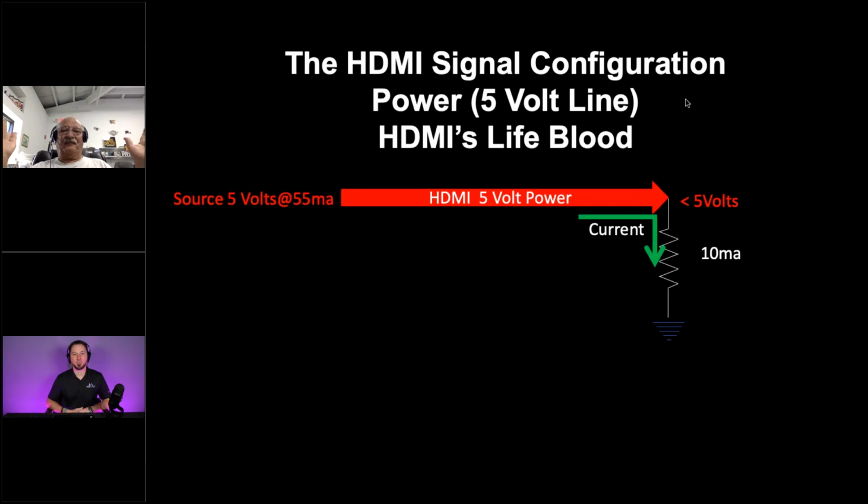So there has to be a simple reason. I'm just not getting the light bulb. It's a very simple reason, because what HDMI did is they put that 5 volts on there, not only to do the handshake, but so that they could supply current into the TV set. So when it's off, if they have any control processing going on and there's no power supply for it, the 5 volt runs it. So it draws more. That's why it's 55 milliamps. Okay, so that gives you an extra 5 milliamp buffer. Well, that AOC we just talked about, well, we just blew the doors out. It's toast.